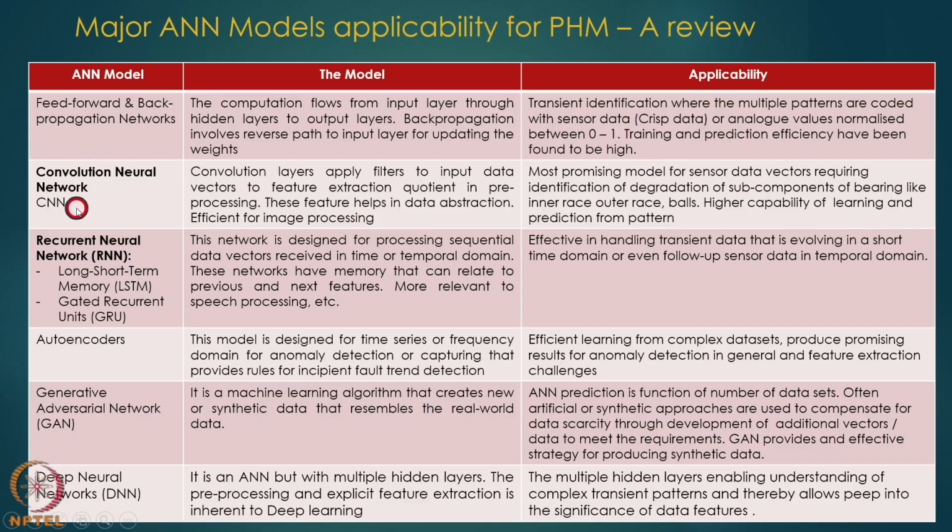Then this convolution is very good for pre-processing and abstraction of features. It is the most promising model for sensor data vectors requiring identification of subcomponent faults in a bearing, like inner race, outer race, and ball failure, with high capability of learning and prediction.